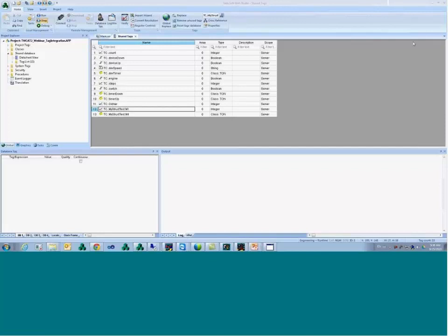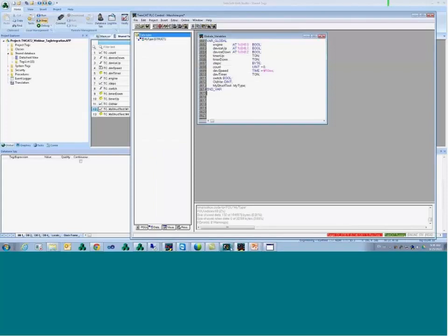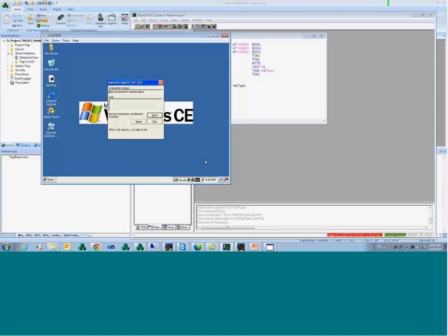So I got a question: if I'm using a simulator implemented with TwinCAT software to connect the tags. No, actually, with TwinCAT I don't have to have the simulator, because as I install TwinCAT, I have the runtime everywhere. So what I'm doing on this computer here specifically, I'm talking to the runtime that is running on Windows CE, on this Windows CE device here.